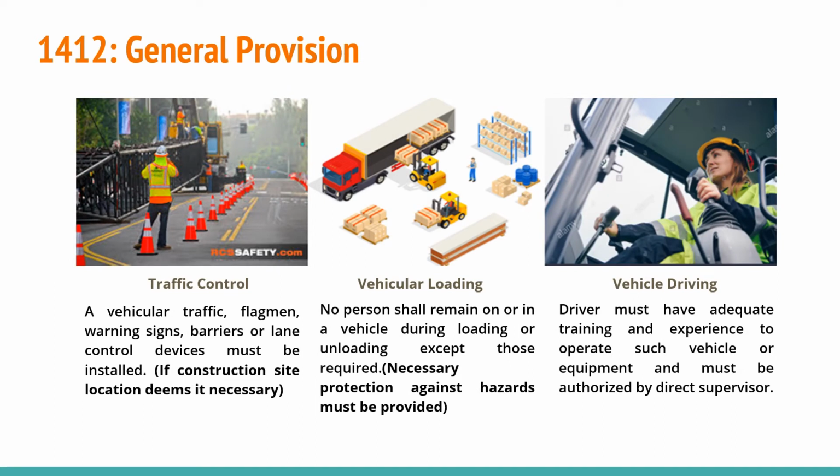So, traffic control. If your work will affect the roads, flagmen, warning signs, barriers, and control devices are essential for the safety of workers and the public. When using vehicles or vehicular loading, while loading heavy materials, safety gear shall be provided and no person shall remain inside the vehicle if possible. And vehicle driving. It is important that the driver must have adequate training and must be qualified to drive certain vehicles. They must have the permission of their supervisor to drive certain vehicles.